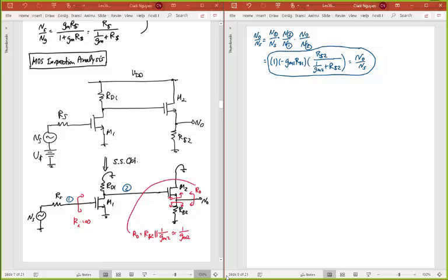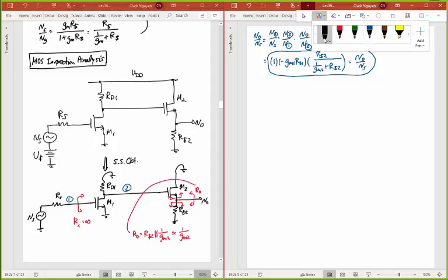I'm done. So I just did the mid-band analysis here, and I was talking doing this. It took me a couple minutes, but in reality I could have done the whole thing in just 1 minute or less, all of the stuff. So that's great. This is the gain equation that we end up with. But let me just say, if you look at this, the way that I've drawn this circuit now, I have not shorted my source to my bulk here. Okay? So I did nothing of the sort there.